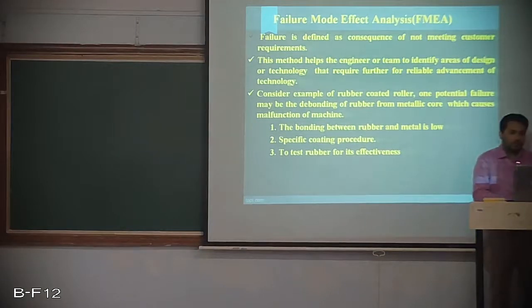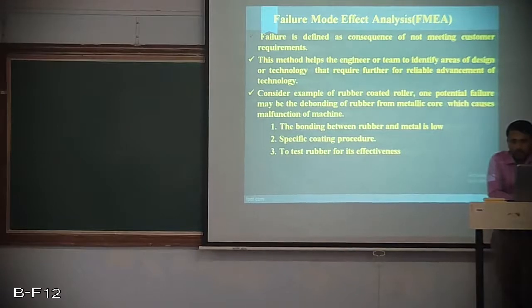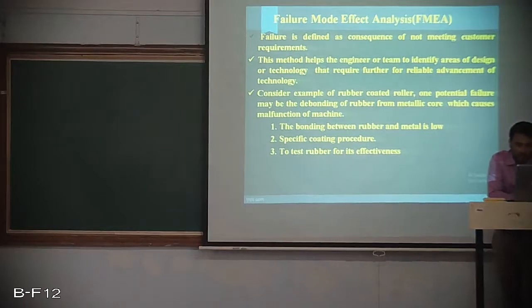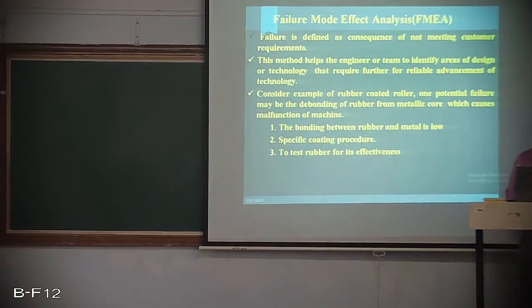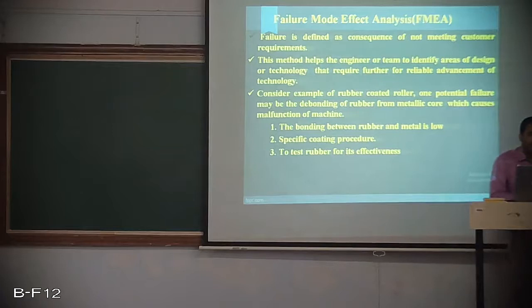FMEA. This topic we left in the third or fourth unit because we need to consider it in this chapter also. So I have left it over there and I am covering it here. Failure is defined as the consequences of not meeting customer requirements. That is true. When you say a component is going to fail, it is not meeting the customer requirements and not doing its intended function.